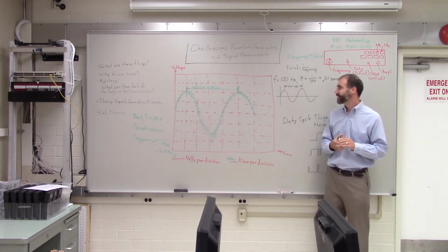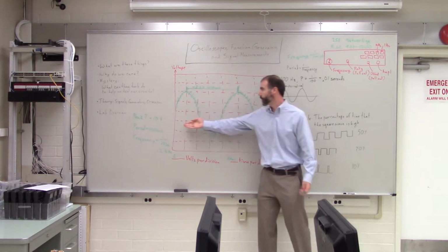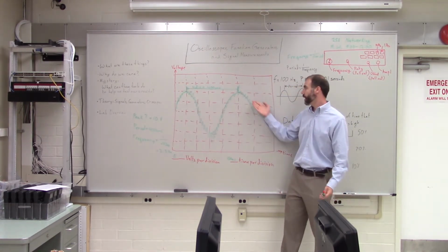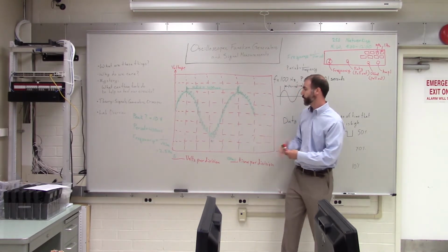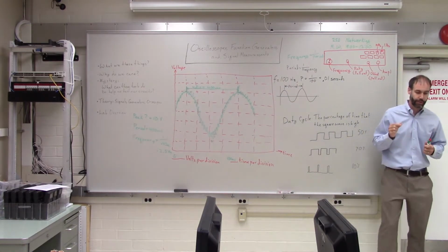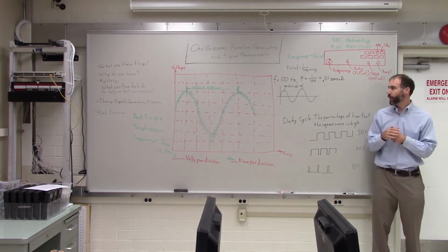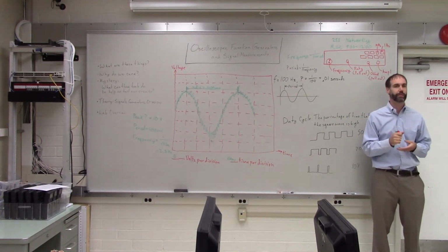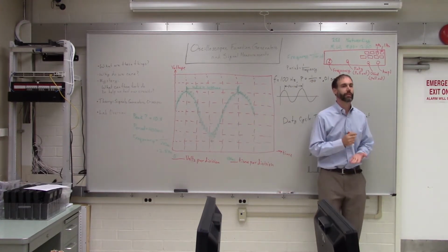Yeah, it happens. So that's why it's important to be able to look at the screen and get a general sense of what you think your signal measurements should be, and then you can use the scope to be a little bit more precise and get some finer grained resolution on those measurements. So any questions about how to get the big picture here?